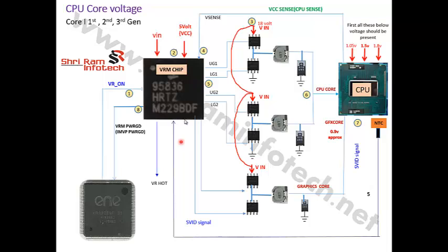And suppose sometimes the CPU is hot or this NTC is open, then this circuit won't work. Okay, so like that there are two criteria. One, the CPU should be present, number one, then the NTC should be proper, that is all, 0 volt. Okay, the next is my VRM section is ready to work.